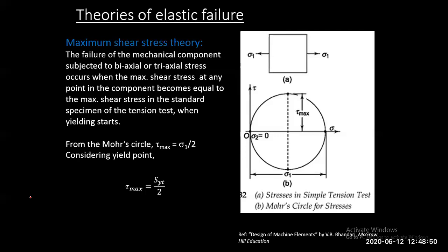These equations are also available in the data handbook, so you don't need to memorize them by heart. This theory you need to know: failure due to maximum shear stress. At any point in the material, if it exceeds that value, it fails. That's what it says.